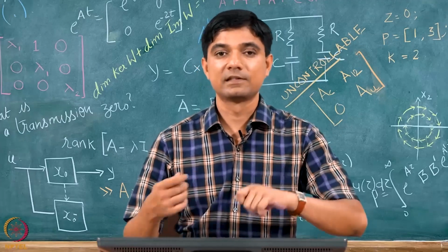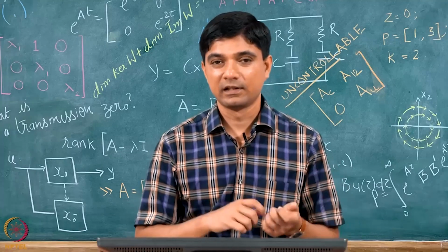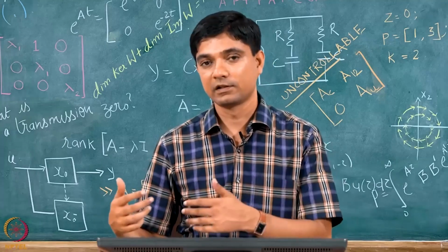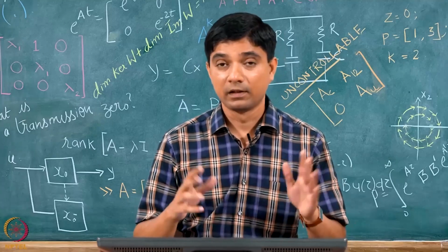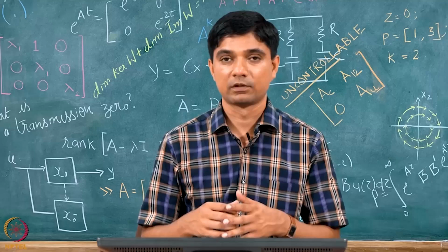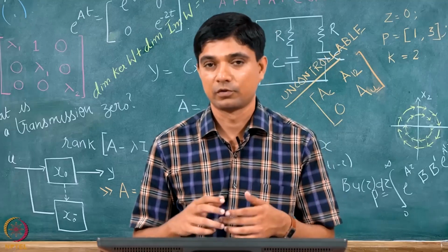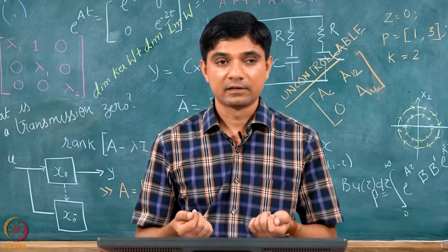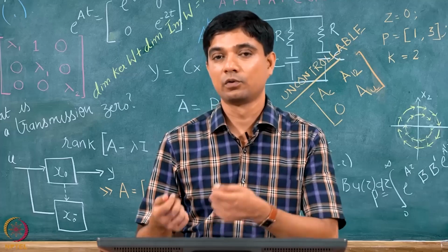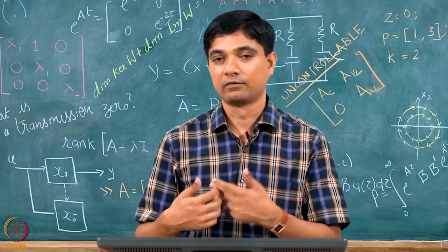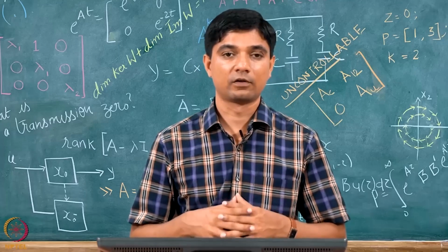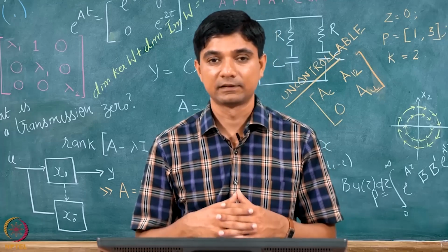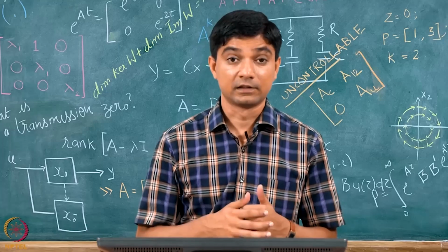Change of basis essentially means how do I change from a controllable canonical form to an observable form or a diagonal form and so on, or given any state space representation, how do I go about deriving one of those canonical forms. And the basis of that, or the mathematical tool for that, is what we call the change of basis.